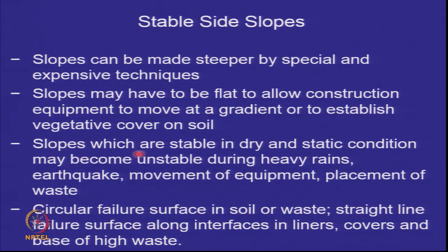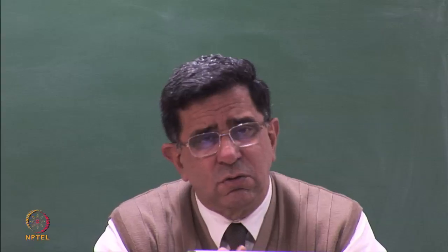Usually when you do the slope stability analysis, you'll find that the slopes are pretty stable in the dry and static condition, but they do become unstable during heavy rains, earthquakes, movement of equipment and placement of waste. And these are the critical conditions which have to be analyzed. And we are used to,